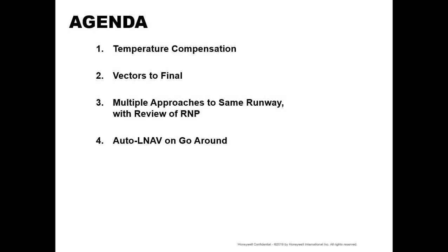In this video, we will be discussing temperature compensation, vectors to final, multiple approaches to the same runway. We'll also review R&P requirements and chart naming conventions, and auto LNAV on go-around.